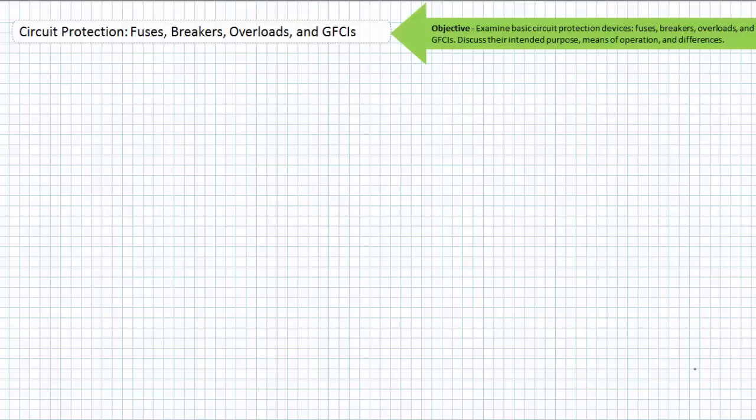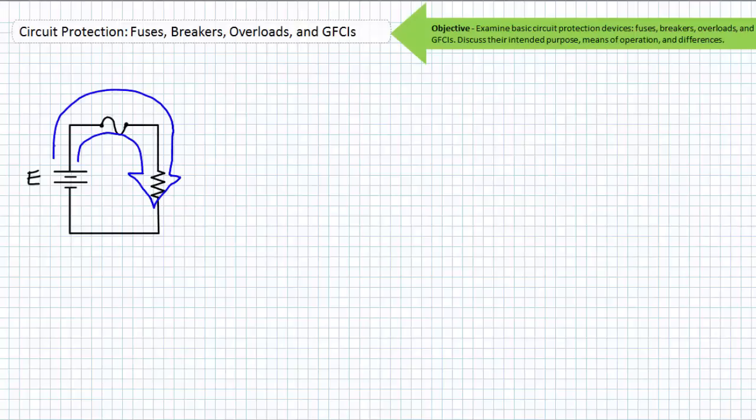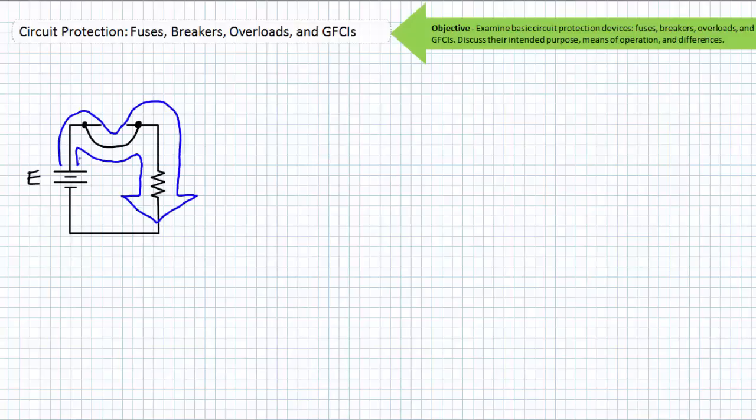Fix the problem. Do not think for a moment that inserting a fuse with a higher current rating is an acceptable solution to this problem. Current in the circuit will reach this higher, potentially more dangerous current, and then the fuse will blow again. Additionally, do not think that by jumping or bypassing the fuse with a wire the system will function as intended. Without circuit protection, the system will burn itself to the ground.